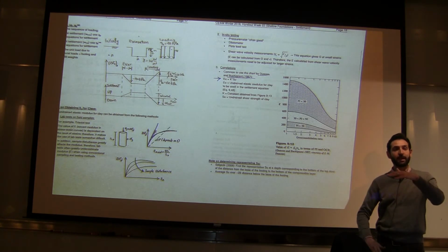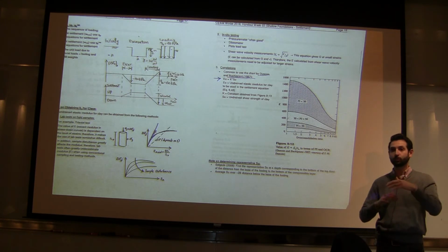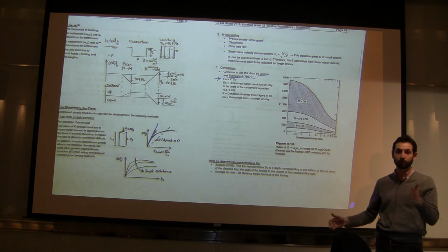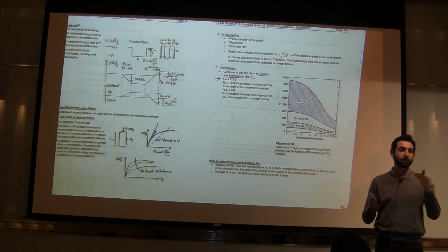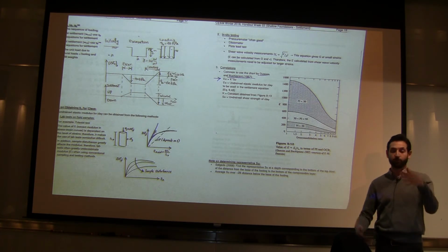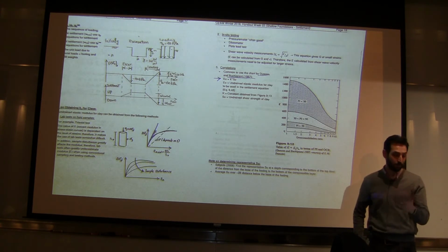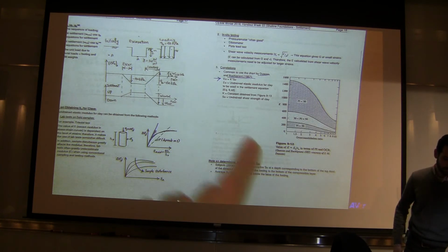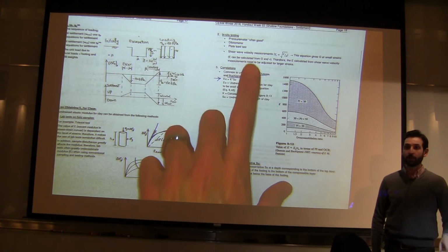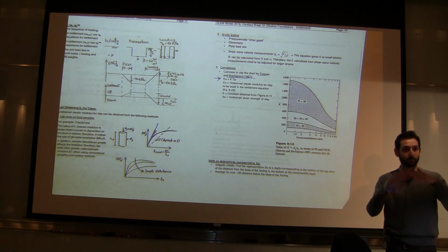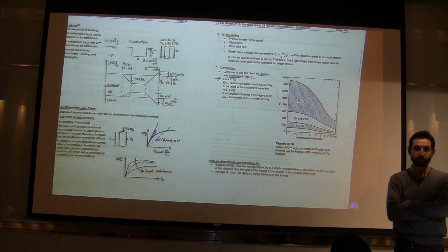How far deep should I average SU? Over 5 feet deep, 10 feet, 20 feet, 100 feet, 1,000 feet? As you get deeper, SU is going to increase. So if you average SU over really large depth for a 5 feet width foundation, you're going to get really large SU, and that will give you a very large EU, and you plug in a large EU in your equation, you get a very small settlement. So it's not conservative to average SU over larger depth.